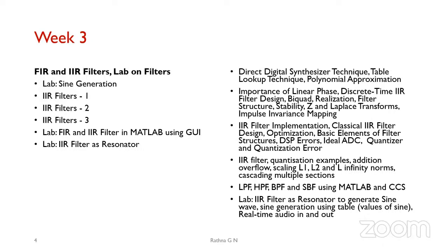So the next one is how to avoid this quantization, because overflow is going to happen. From stage to stage, you may have overflow. Then at each stage you may have to avoid the overflow. For that we have to do the scaling.